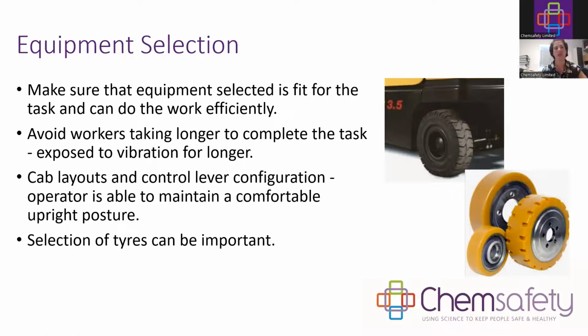And then also very important with equipment selection is taking into consideration the cab layout, whether the controls are high or whether they are hard to access, so you have to do frequent twisting of the back, or you have to lift your elbows and your shoulders at uncomfortable positions. And then also the selection of the tires is very important. So as a rule, the harder the tires, the more vibration you'll have, or likewise with the shocks. If you don't have sufficient shocks on your mobile equipment, you'll have higher vibration going through the seat.